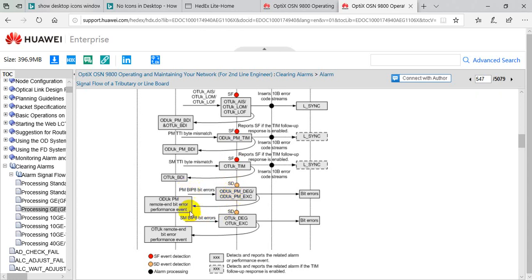So this is the PM byte. Similarly, the SM byte is also read with this ODU frame. This was the ODU overhead byte, but the decision and calculation methods are the same, and these will be reported back. So ODUK PM remote and bit error performance events will be considered as captured in terms of performance events at the ODUK layer as well as the OTUK layer.